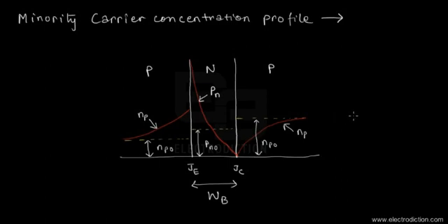You can see the P type emitter section over here, I'll write this one as the emitter, that's the base, and here's the collector. So in the emitter, the electron concentration in the thermally stable condition is denoted with this dotted yellow line